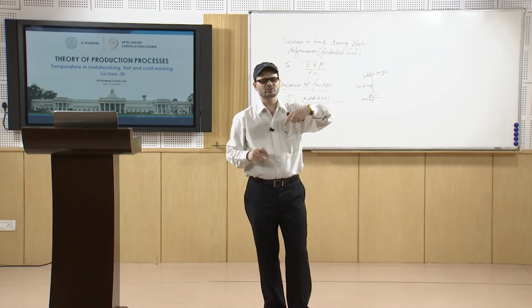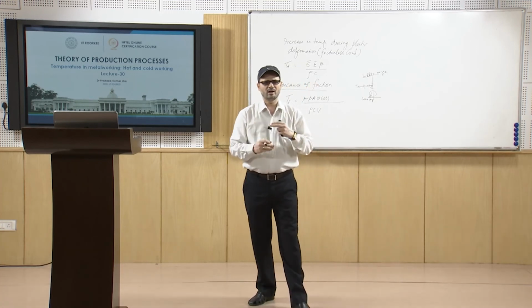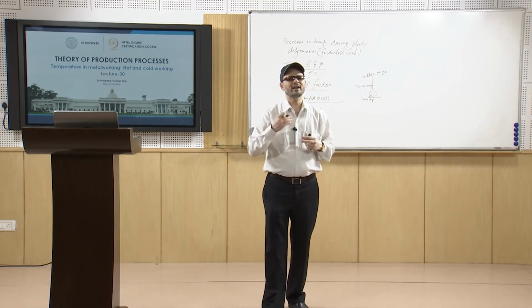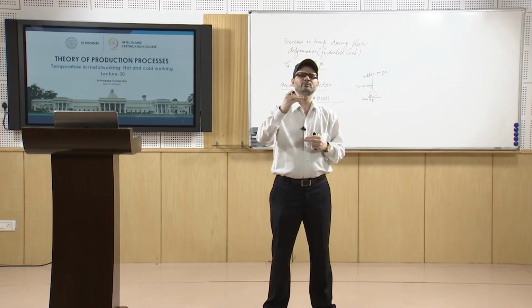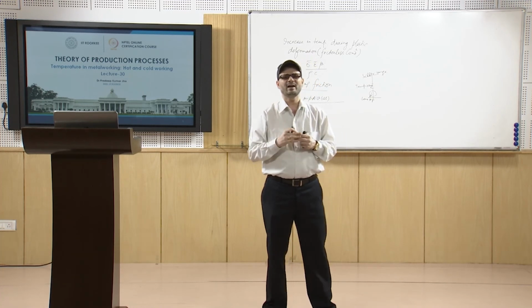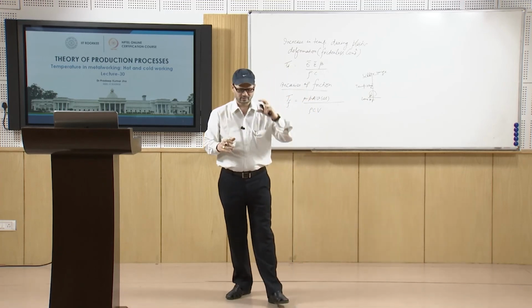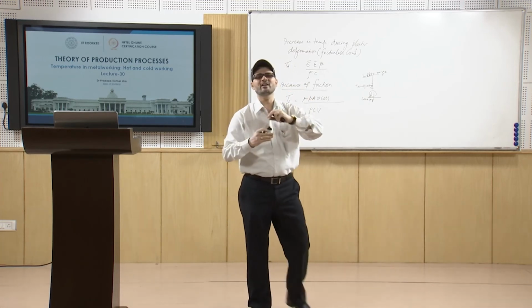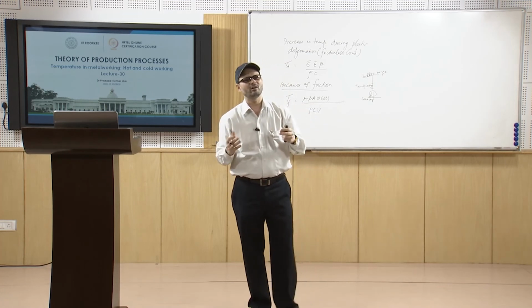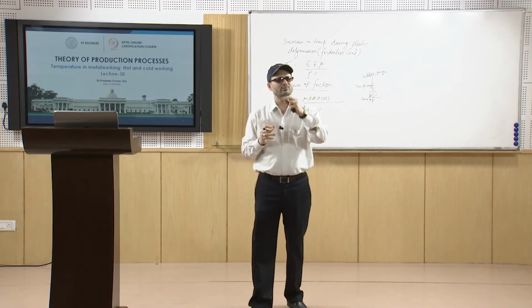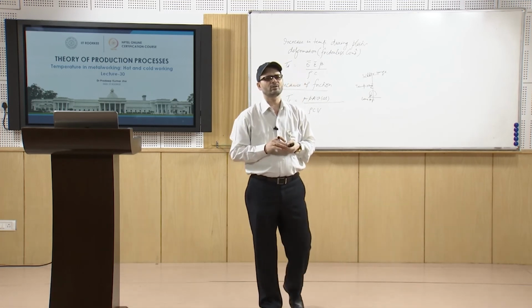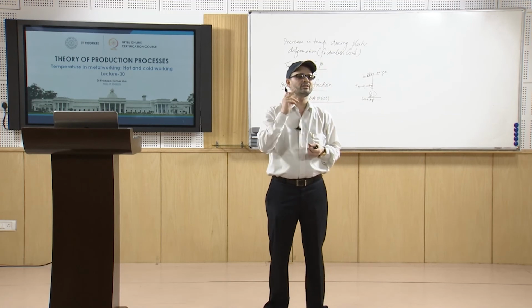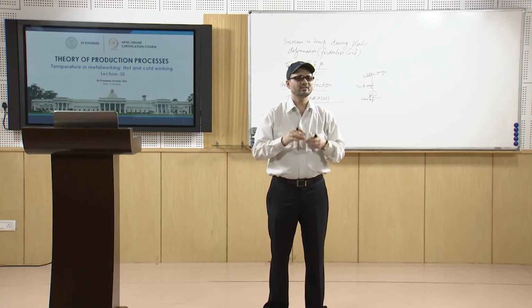Normally, as you go on deforming in cold working, because of strain hardening the flow stress requirement goes on increasing. So, if you try to deform more, there may be a situation where the stress generated inside the material is more than the yield strength, and the material may fail or fracture. For avoiding that, we do the annealing operation in between. Although it increases the forming cost, it also increases the versatility of the process.